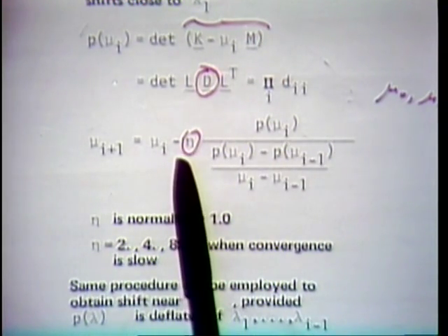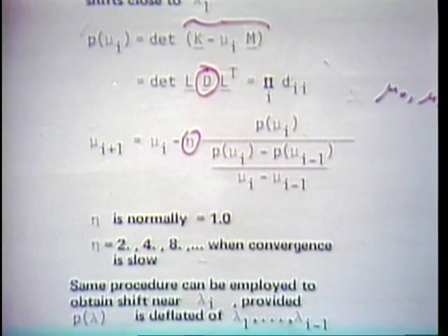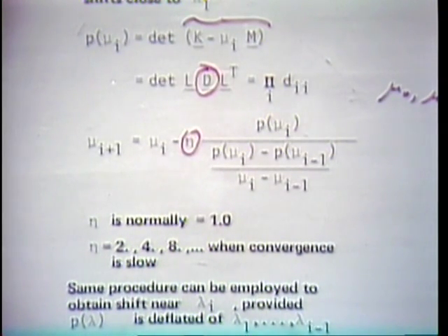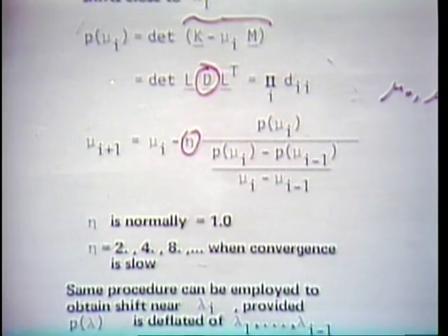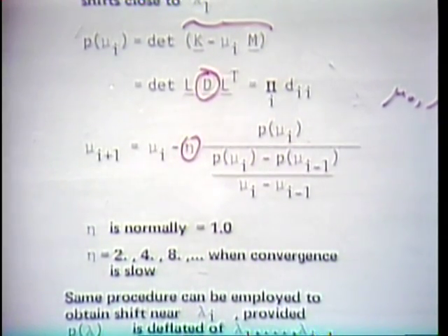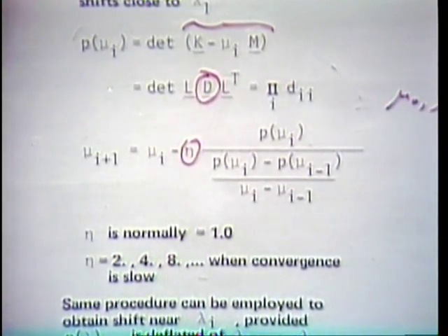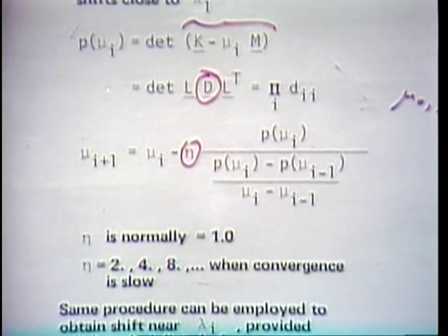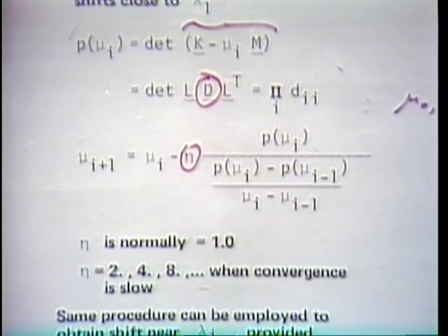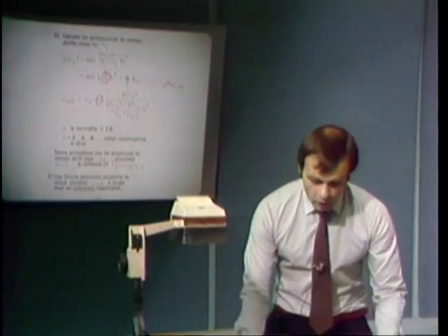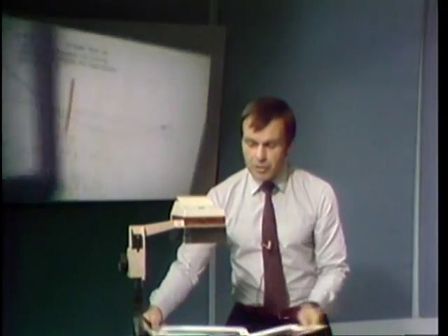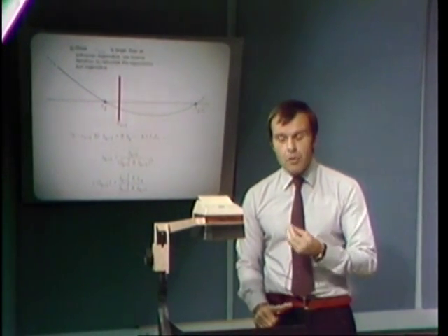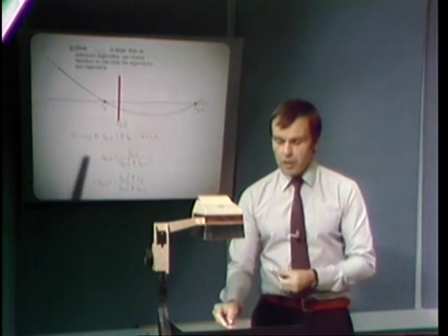And until we find that we are close to an eigenvalue, either from the left or we have jumped across it already. But we should never jump too far, and we're making sure that we never jump beyond that point A. And having jumped, we find that the Sturm sequence count tells us about it. And now we are going on to another strategy, and that strategy is the vector inverse iteration method that I discussed with you earlier.